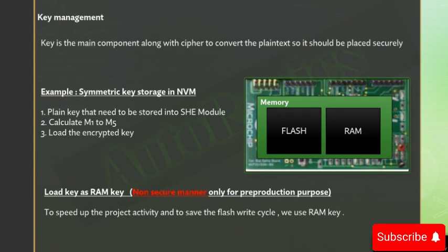Then it loads the key, which has gone through the MAC and encryption process of the key update protocol, into the secure area. As you can see in the image, this will be the flash region, where the flash region will be partitioned only for the NVM secured area. In case